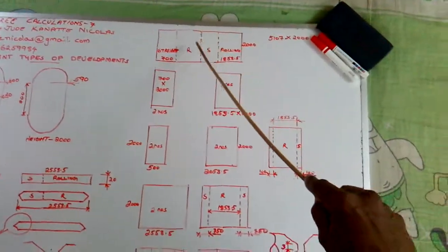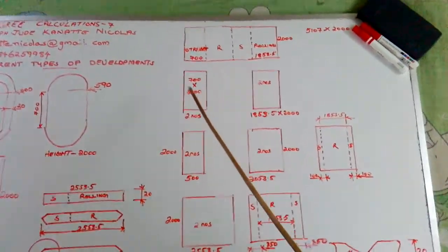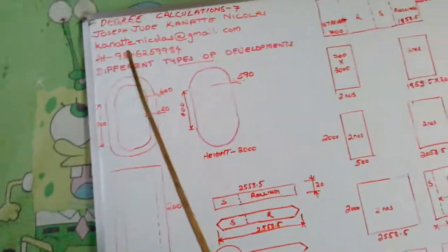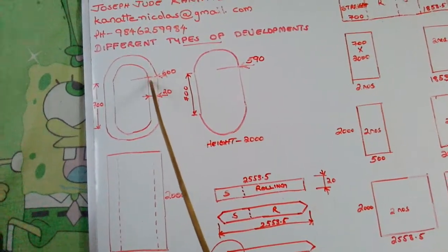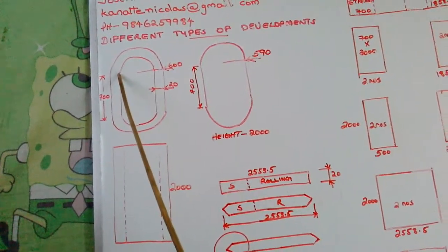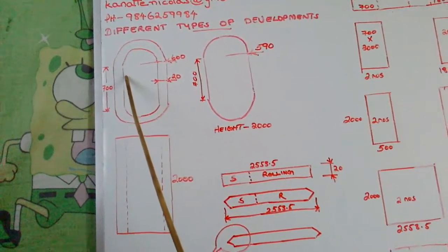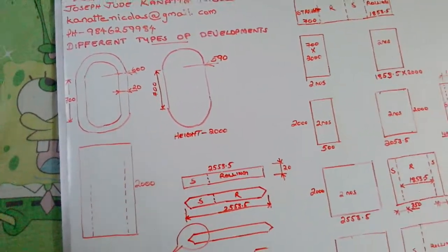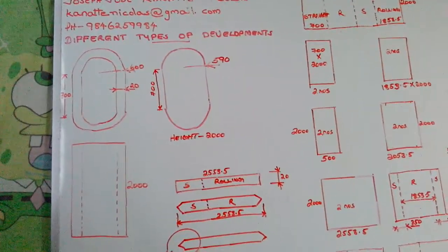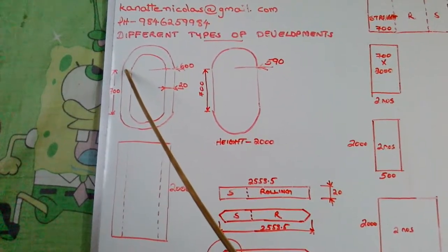So one method is this one, second method is this one, third method I told. When we take this kind of measurement, I told the problem of rolling. When we roll, at the last end of the plates we won't get rolling. I told you approximately 100 mm we won't get. So I had recommended you take 100 more mm from the half round end.